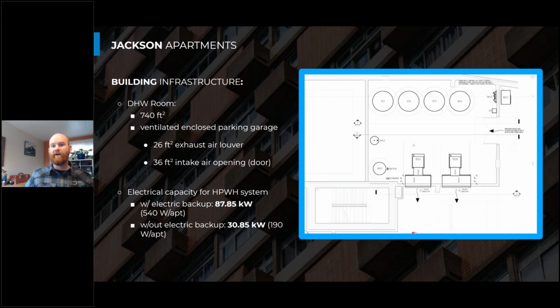And there's a system of garage exhaust fans right about here, just outside this page, that are then exhausting that air outside the building. These heat pumps could also be directly ducted to the outside of the building, but in this design, to reduce ducting and to reduce first cost, we just discharge that cool exhaust air at the garage exhaust fan system, which is operating 24/7 at a lower volume, and then peaking to a higher airflow rate when we have toxic chemicals in the garage like CO or NO2.